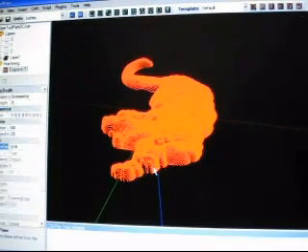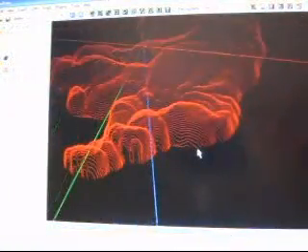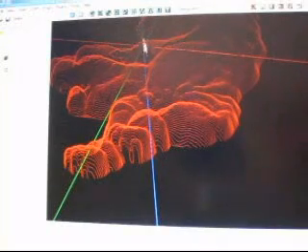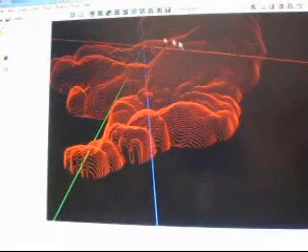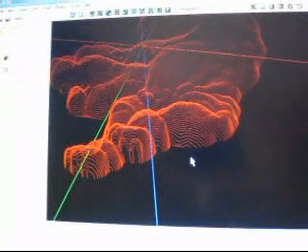And the reason for that is we're tricking this system into doing what I want it to do. Normally I would set the clearance plane above my part, like 0.1 of an inch, so it clears. Now keep in mind, we're not going to run the toolpath like this.